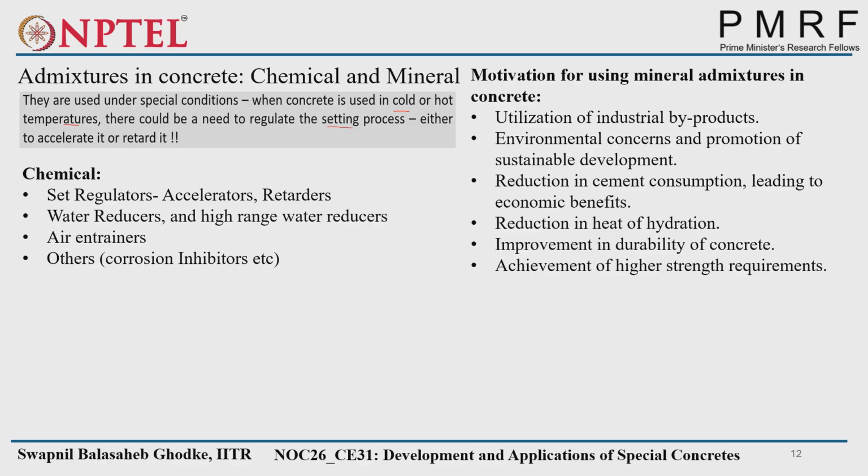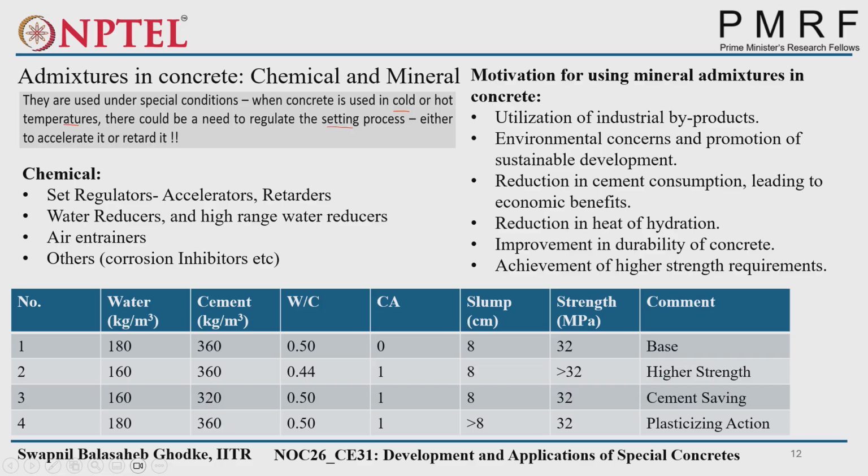Then there is reduction in heat of hydration, which I already discussed. Most mineral admixtures give later age strength because they react directly with CH, which is the byproduct of the major binder component, cement. Then improvement in durability of concrete, because it reduces the pores in later age hydration, and achievement of higher strength because of reduced pores. When pores reduce, ultimately strength also increases.